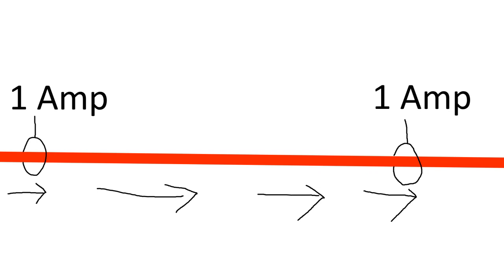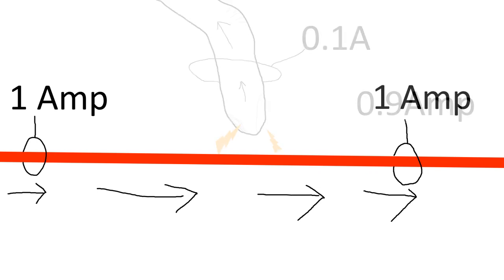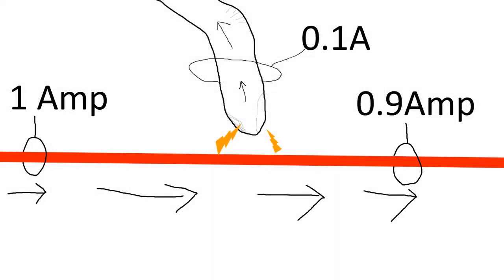You're not going to just get electrons out of nowhere, and you're also not going to just lose electrons out of nowhere. And if you are losing electrons in a house circuit, you probably have a ground fault, because the electrons don't just leave without coming back, unless they leave through ground, usually. Maybe a couple will just disappear, but they're not going to get outside the insulators.